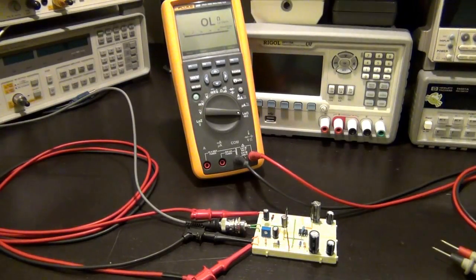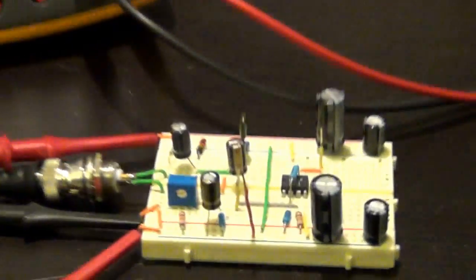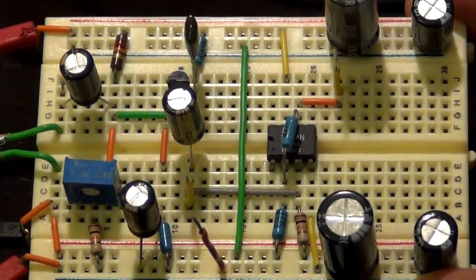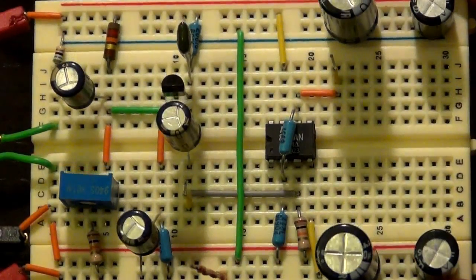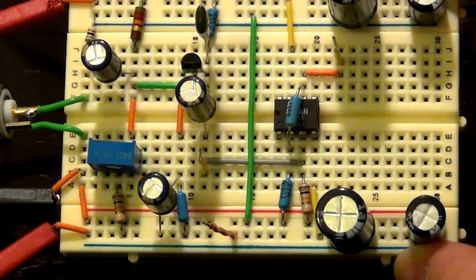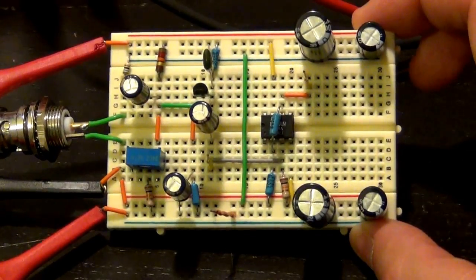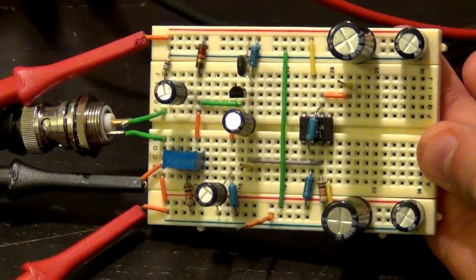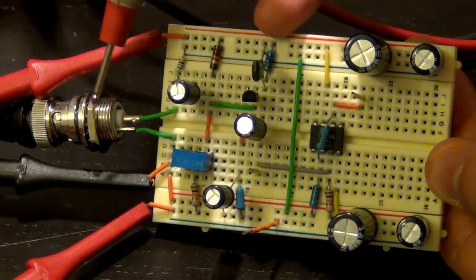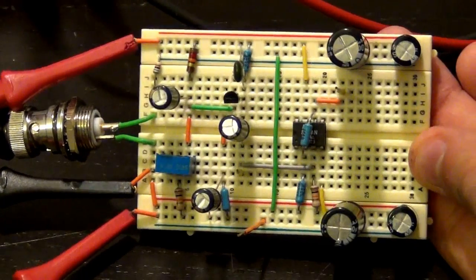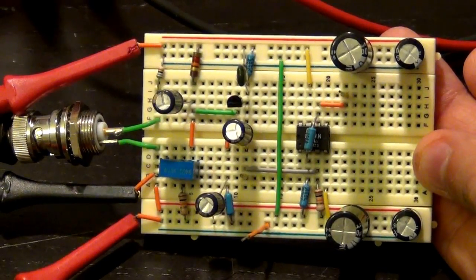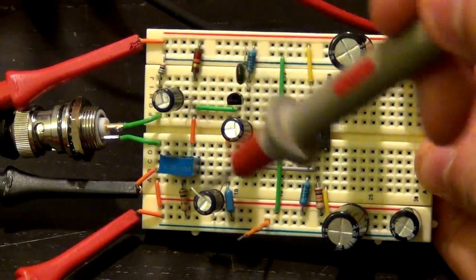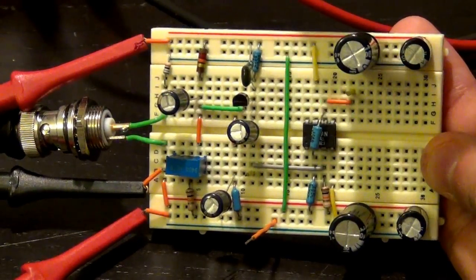Alright, here we go. I have built this circuit that we discussed. Let me show you a close-up so I can describe what I have. So here I have both stages of the amplifier, the op-amp and the bipolar common-emitter amplifier, both of them assembled on the breadboard. At the left side, the input is currently coming from this BNC connector. Right now we're going to first test this using a signal generator before we test it using an op-amp. So here is the input capacitor that decouples the signal generator from our amplifier.